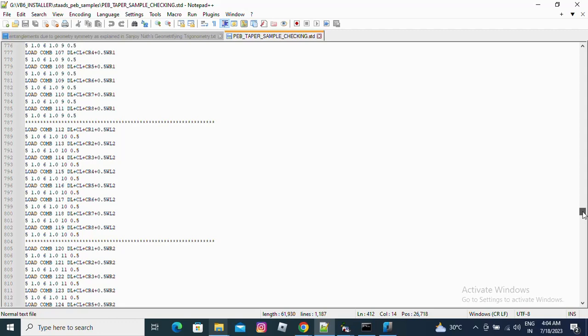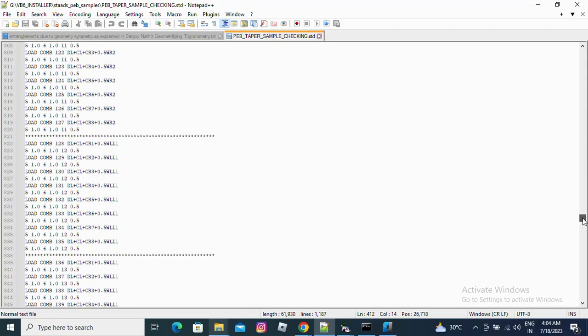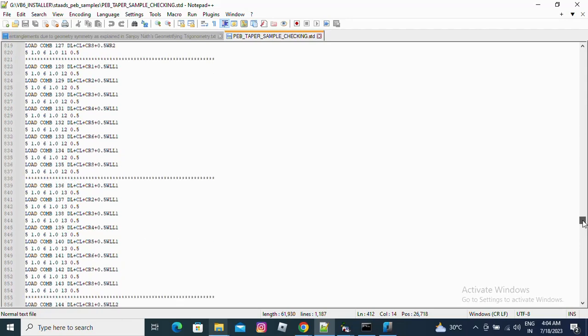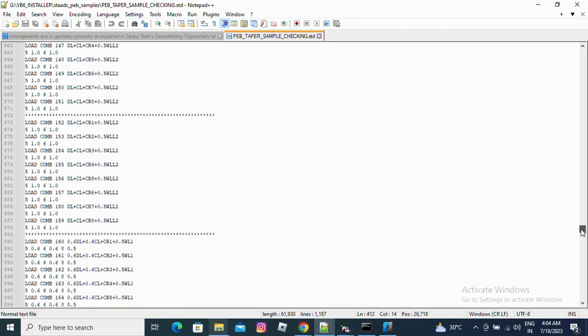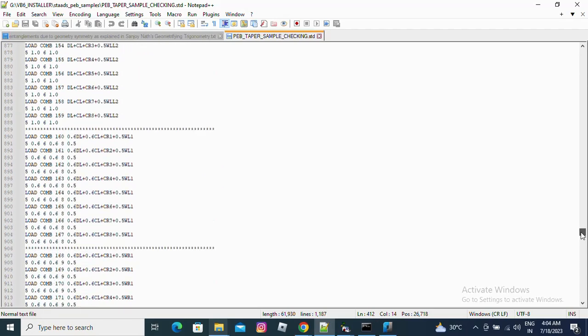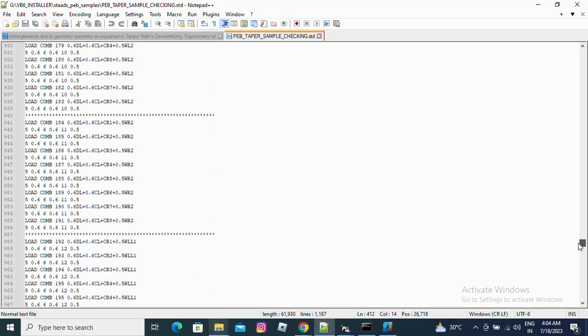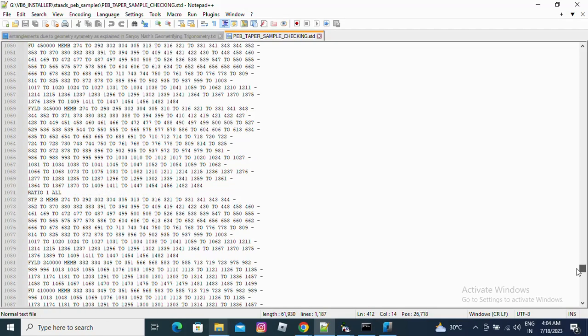It can automatically generate the Tekla importer files for Indian pre-engineered building structures, which are the custom parts of Tekla. And it can also generate the plated models if you want, where every flange and web is taken separately as contour plates. Sometimes people expect those kinds of things also.